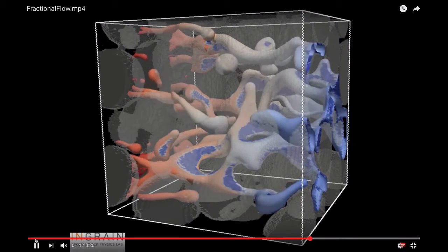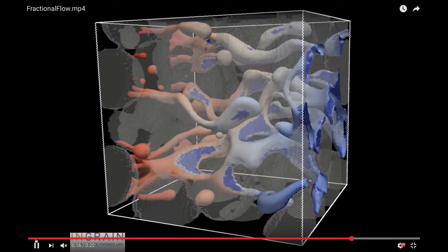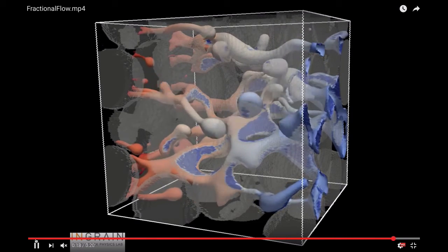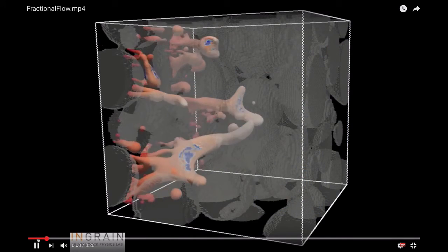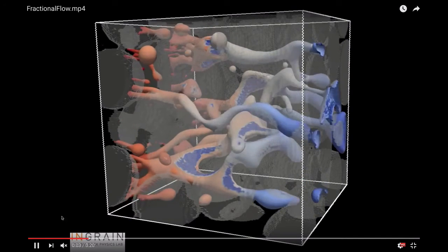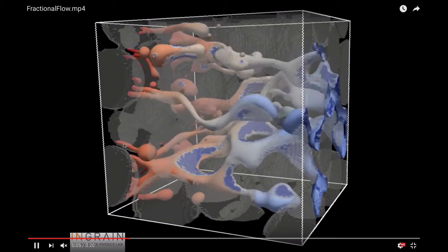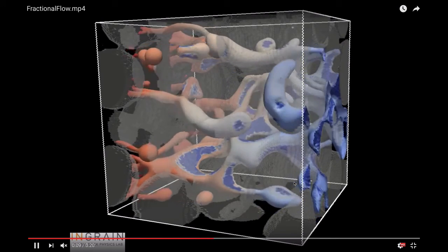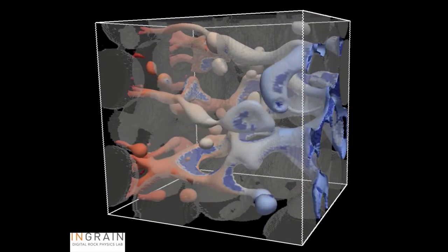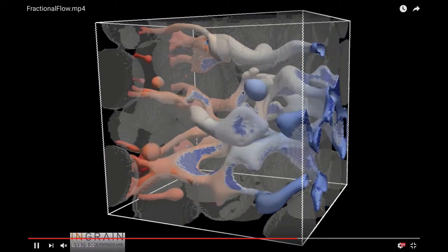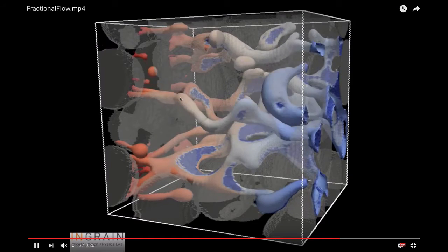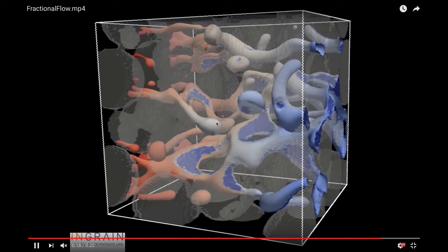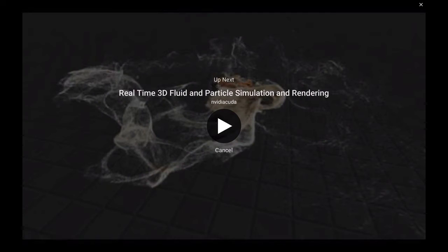But if you solve conservation of mass, you also have to account for the fact that it's a viscous flow and you're losing energy. I think the color scheme in this is that red is for a higher pressure, blue is for a lower pressure on the other face. And so you're using pressure to push this thing across the cube, where these are the individual sand particles, and it's going through the pore spaces only as this multi-phase flow of oil within the system.